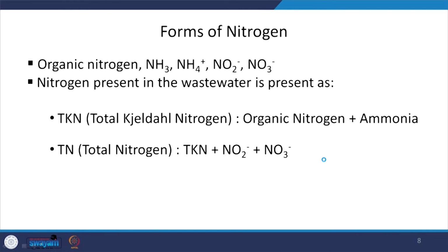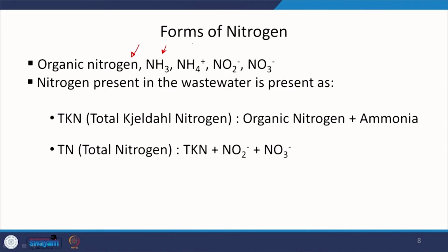So, first, nitrogen removal. What are the forms of nitrogen? We already discussed this in, I believe, one of the earlier sessions, but a quick recap. So, we have organically bound nitrogen, nitrogen that is bound to organic compounds, NH3 and NH4+, right. NH4+ and NH3 are in equilibrium, typically based on the H+ or pH of the solution, and you will have an equilibrium dissociation constant. Again, that is acid-base environmental chemistry, you can look that up. And then depending on the level of oxidation, you can have nitrite, NO2-, or nitrate, NO3-. So, these are the forms we are concerned with.